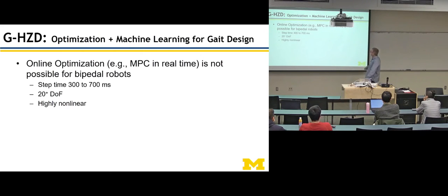It was fast, but not fast enough to do model predictive control. You've heard about that maybe. So with model predictive control, you say, I'm not going to compute my controller offline. I'm just going to do it online, and I'm going to do the following optimization. I've got my model, and then I will minimize some cost criterion subject to constraints, and my cost criterion will be planning outwards, say, 10 seconds ahead of where I am, or maybe a minute or something like that. So it's finite horizon, etc.